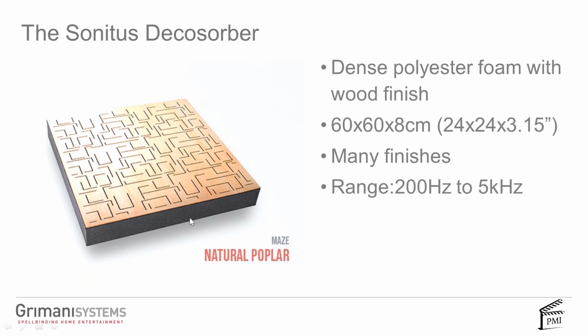Ted Schultz, a really well-known acoustician, really quantified this. There's a whole bunch of data and equations, but it's basically how big of an area you have between the perforations for a wave to bounce off. This area in reality is about 2 inches, that means an inch and 3/4, something like that. That means that a wave, let's say above 4 kilohertz, is going to bounce off that. Or in this region, it's going to absorb, but this is going to bounce some energy, reflect some. It's going to scatter some energy. It's a little complex, but you've got this in your toolkit.